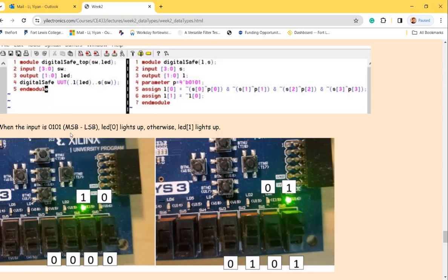So you are going to explain what this system is being used for, and design, write the Verilog code, and implement to FPGA and do the demonstration using switch and LEDs. You can also use push buttons. It's very similar, but make sure that the push button part of the constraint file is getting uncommented, so they are available for the synthesis when it's generating the bit file.